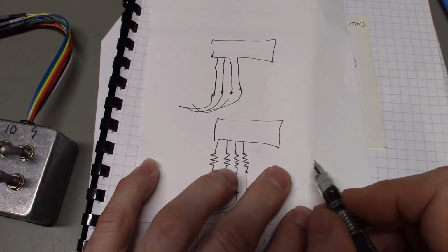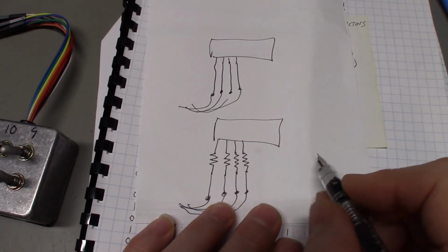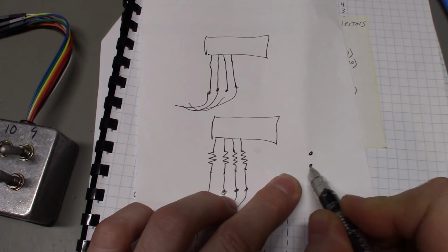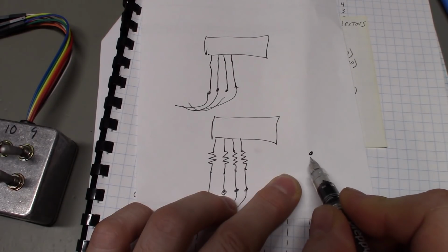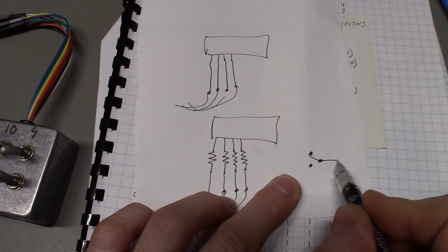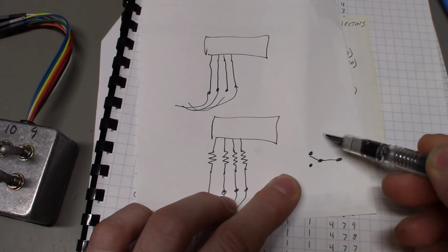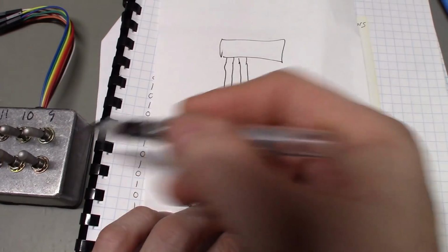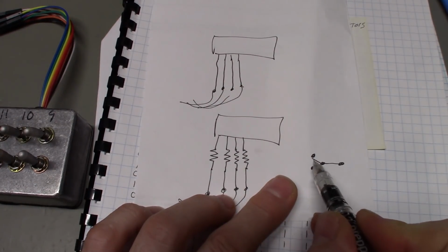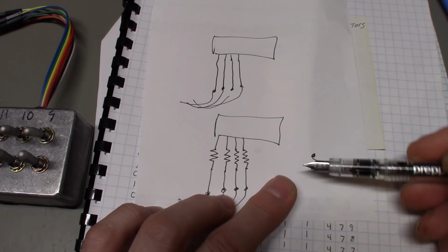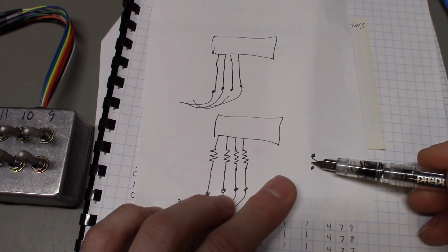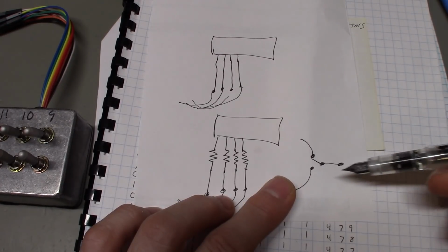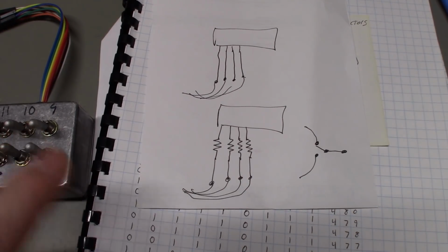We'll just pick one of them. I'm not going to draw out all 4 of them, but you'd have your toggle switch contacts. So that's the toggle switch where it actually flips. And remember, these are 3 position switches, so this bar right here is the part that flips, and it can actually be in the center. If it was in the center, it doesn't touch either contact, and there's a wire attached to each of those terminals. So these toggle switches have 3 terminals.